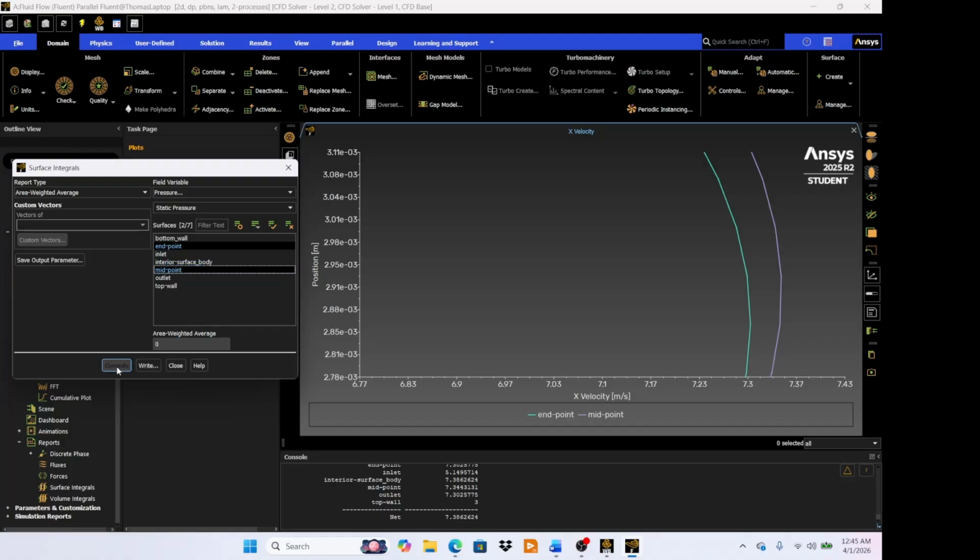We're going to click compute. And now that gives us our static pressures, which we are going to use to compute our pressure gradient, which ends up being -37.534 pascals per meter, where through theory I got -38.64 pascals per meter, which is right around what you're expecting. And so that should be everything you should do. Thank you again for watching.